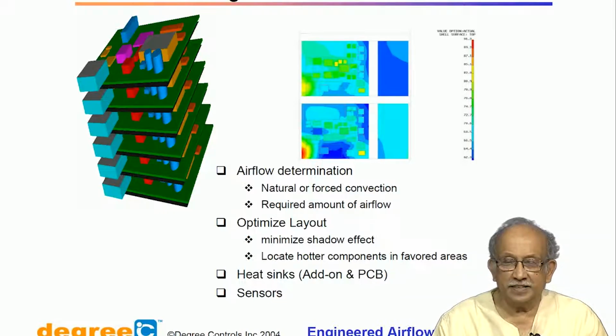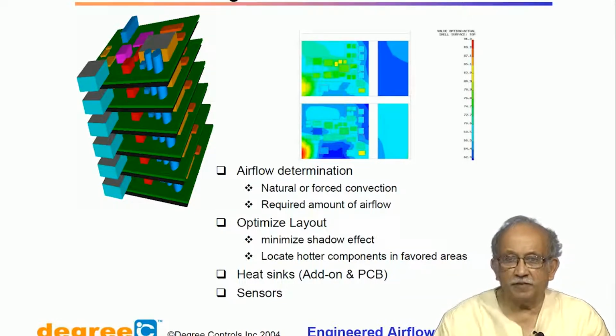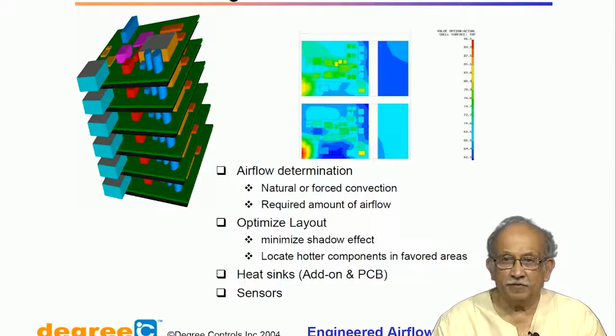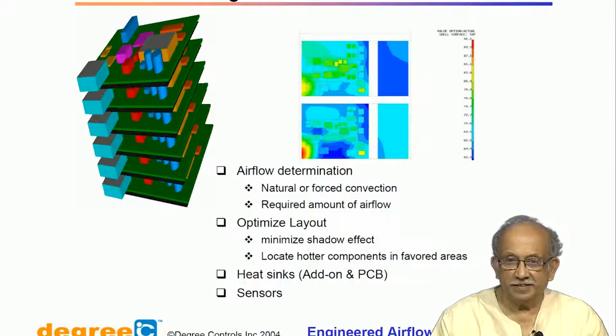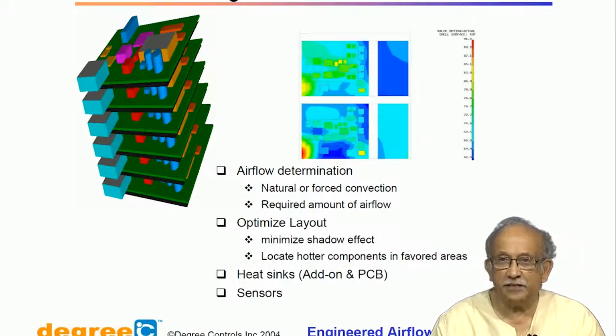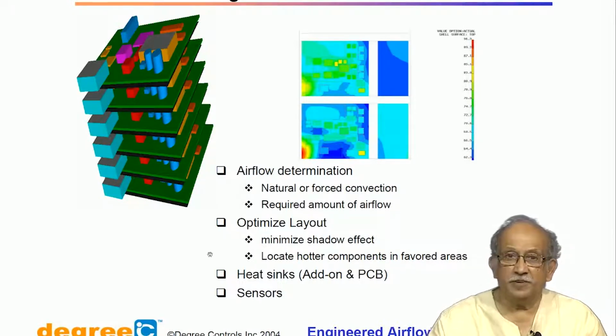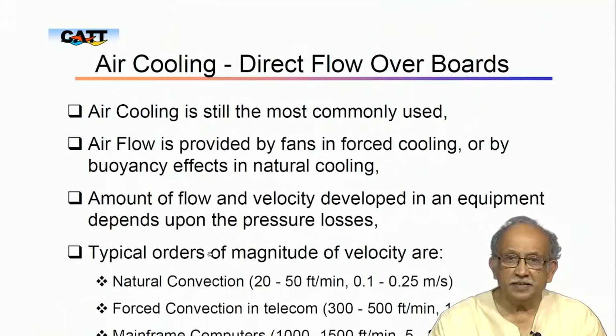You notice that the chip itself probably has a way of measuring its temperature, and then that is given to a fan, and the fan can run at 2 speeds. And why not the higher speed all the time? One nuisance is the noise. The noise is so ridiculous that you cannot afford to keep the fan running at all the speeds.